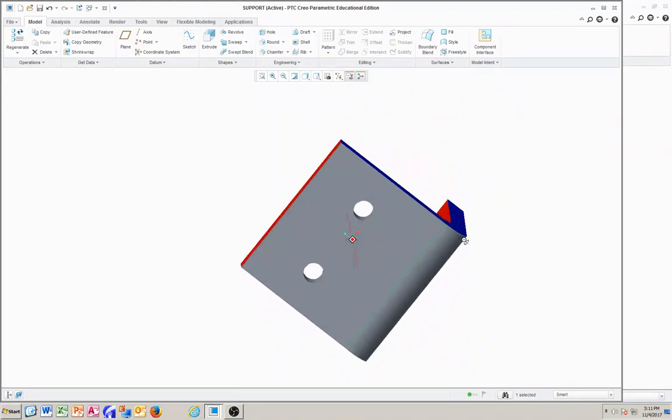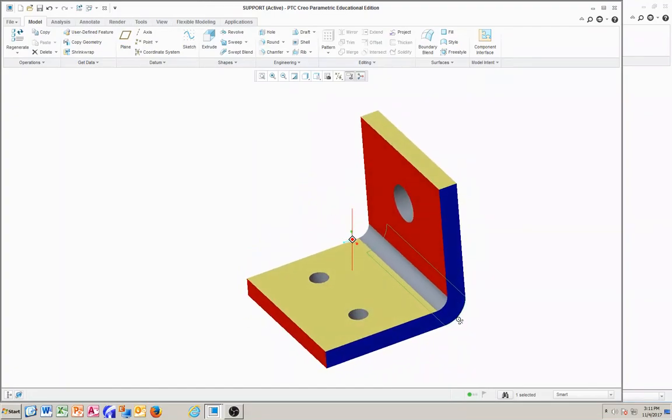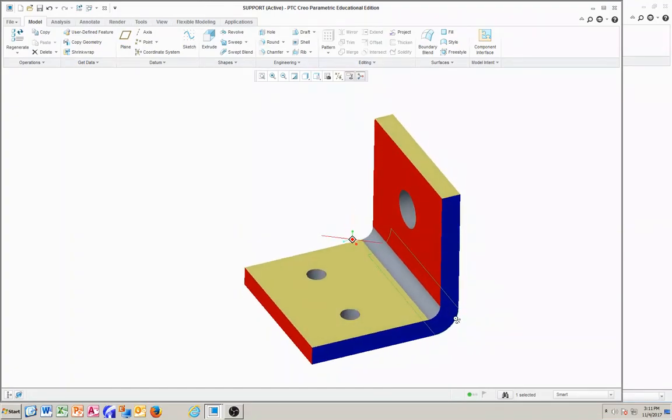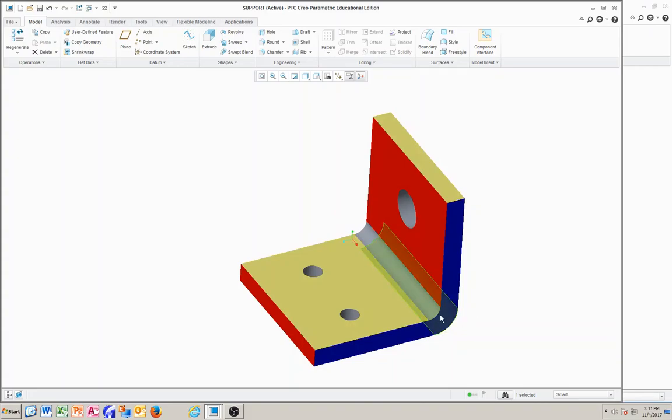The reason we put the fillet, when we have a bracket like this, is that upon impact, if it's a sharp corner, it's going to break. Adding a fillet radius improves the strength or stiffness, or the resistance of this material to fatigue, and it's going to prevent this material from failure if it is subjected to cyclic loading. So adding a fillet radius is going to improve the fatigue life of this part.